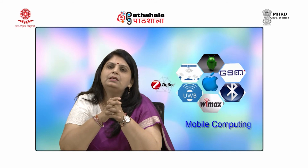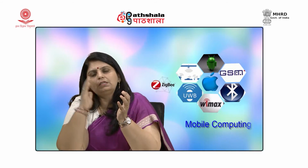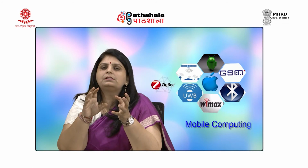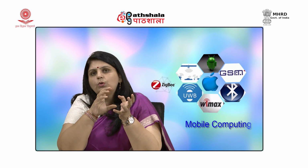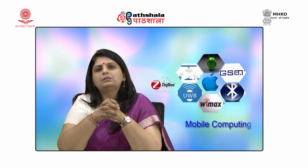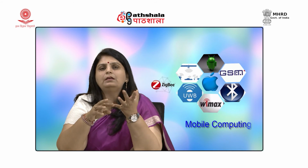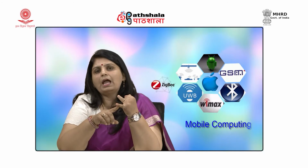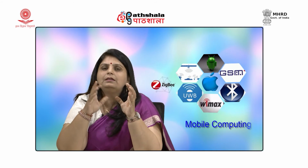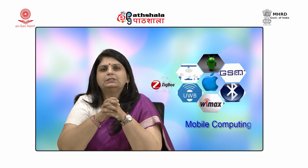So, instead of taking a single path, the signal is taking many paths, and those components which are taking different paths are known as multipath components. They will arrive at the receiver at different times, with different amplitude and different phase, and this phenomenon is known as multipath propagation.